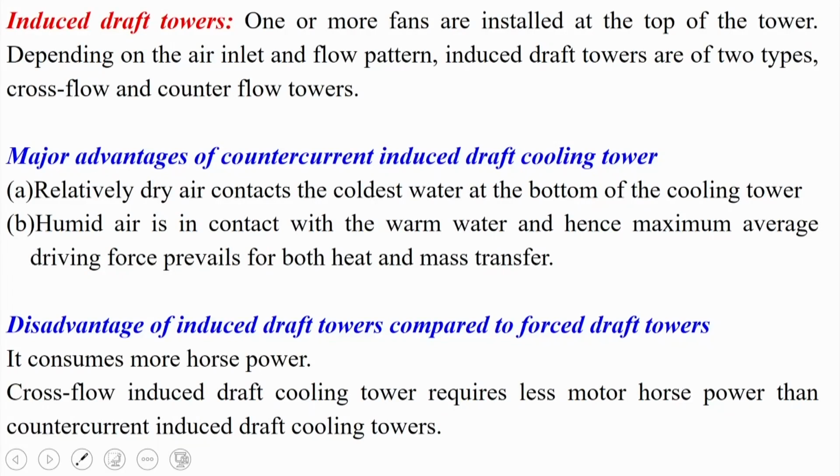but some disadvantages also are there in the case of the induced draft cooling towers compared to the forced draft cooling towers. It consumes more horsepower, and the cross flow induced draft cooling tower requires less motor horsepower than the counter current induced draft cooling towers.